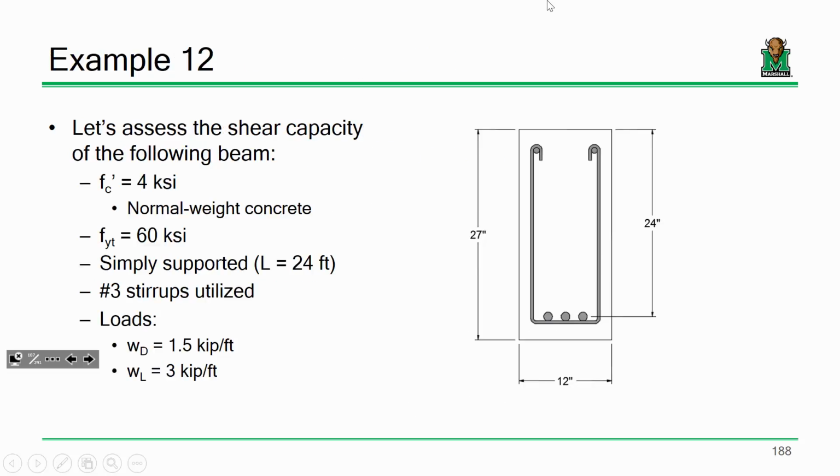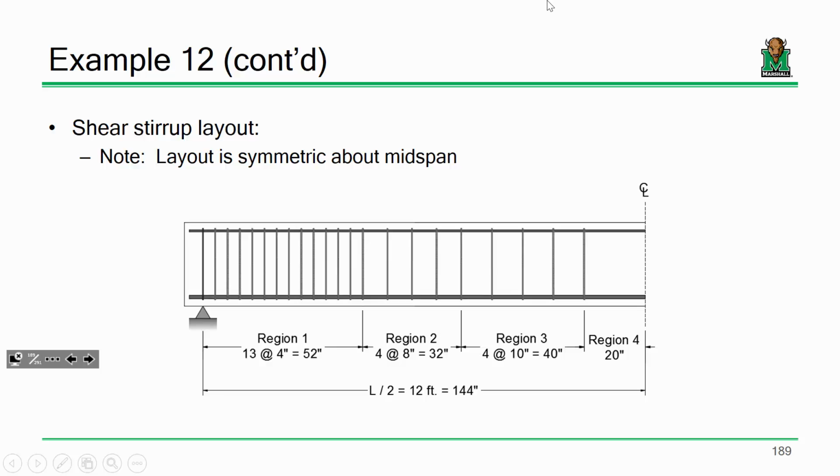Now, there are provisions for taking a stirrup and actually inclining it along the crack to resist it better, but these just aren't really going to do any good. By the time you've cracked through all of this, the beam's done. I see what you're saying, but from a safety standpoint, if you've got a full depth 45-degree crack going right through that, beam's done.